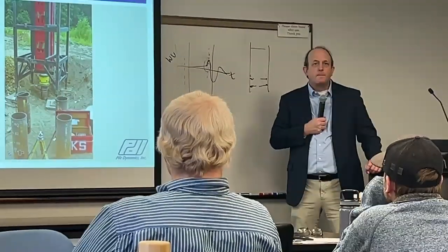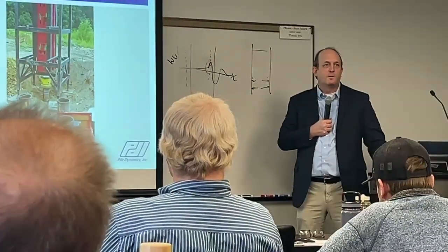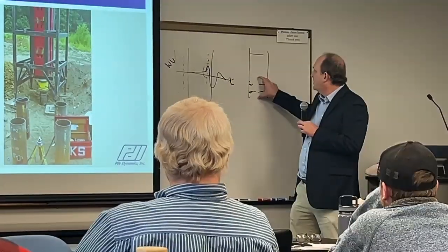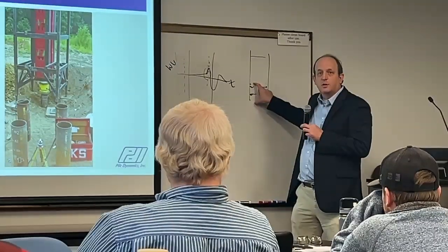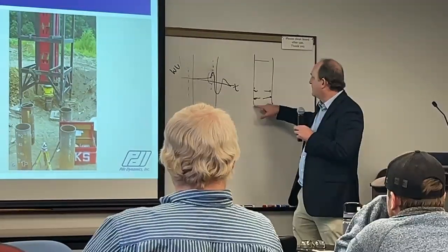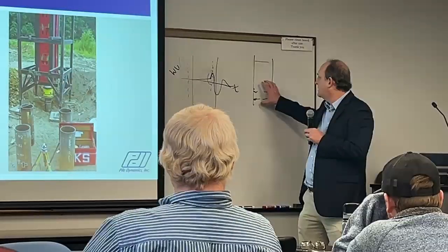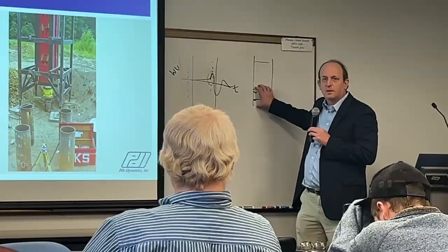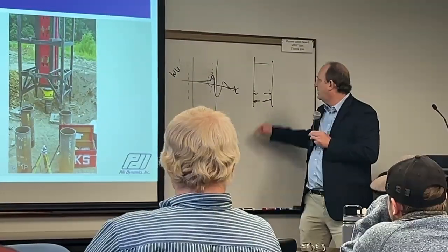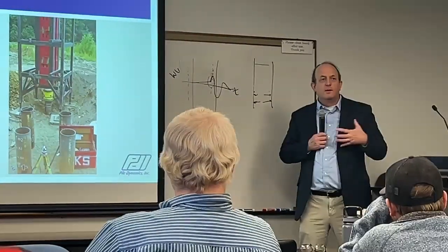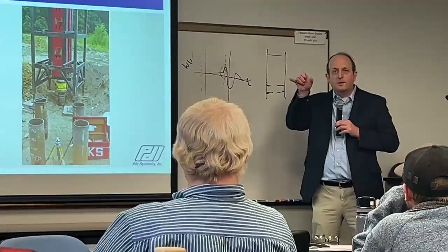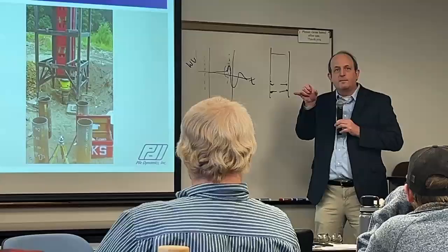And when Frank Rausche looked at that in the wave equation, he noted that this soil here has an inertia, and if we can get it so that the resistance forces are bigger than the inertia of that soil as the pile is being accelerated, we can get a plug. But if this is accelerating quickly, the plug doesn't want to move. It wants to stay at rest. And so that's when you get a resetting of the coring type behavior that comes out of that.